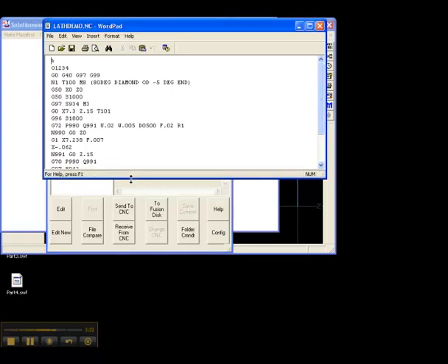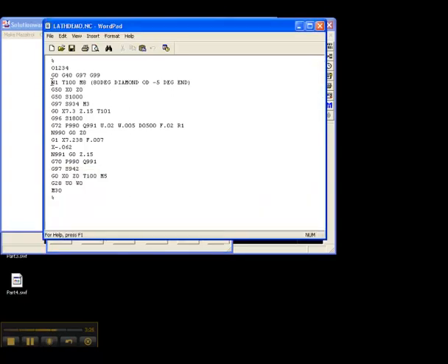Here's the G-code program. We only have one thing going on here. You can see it calls up tool 1. I'm sorry, here this is prepping tool 1. This is no offset. Here we have fixed RPMs, just to get the tool close apparently. And then here we're actually calling up tool 1. Here is the constant surface speed on once it gets close to the part. And then this is the canned face rough cycle, the G72. Going on down here, this is the canned finish pass. And then it puts the tool away, cancels the tool, and M30 calls it a day.